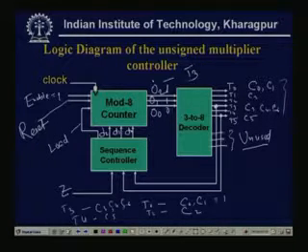When these conditions occur, the counter must be loaded with external value 0, 1, 0 at the trailing edge of the next clock pulse. T2 equals 1 only when O2, O1, O0 is 0, 1, 0.